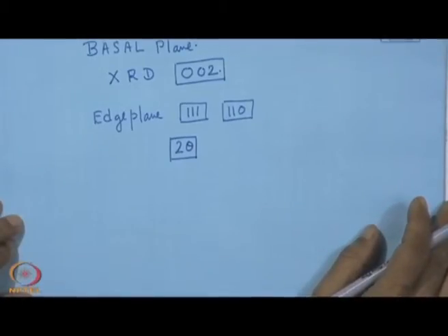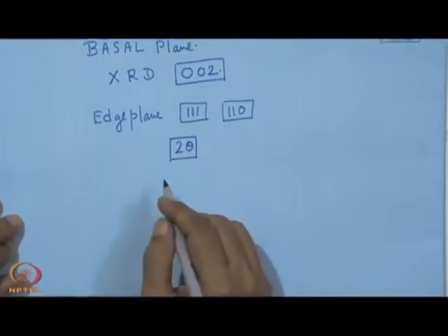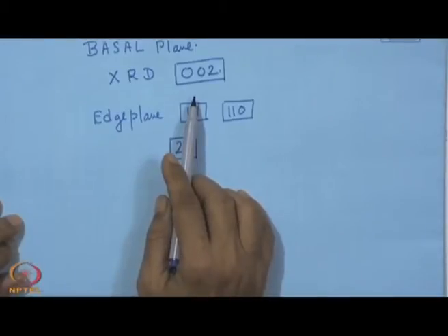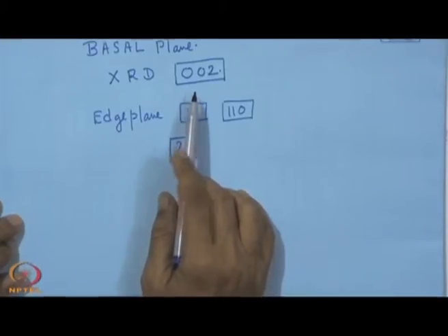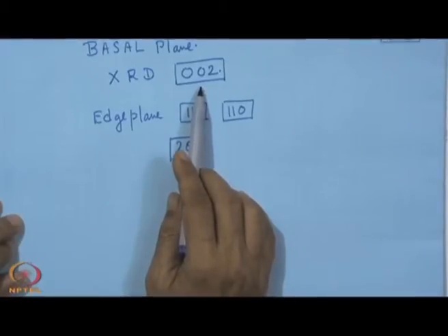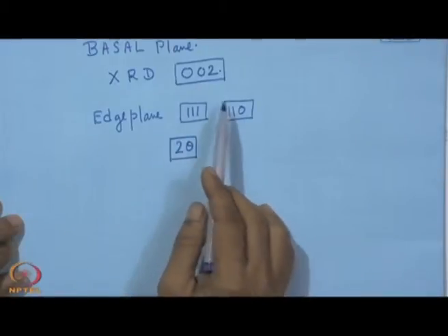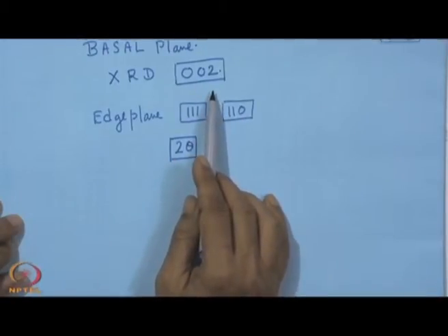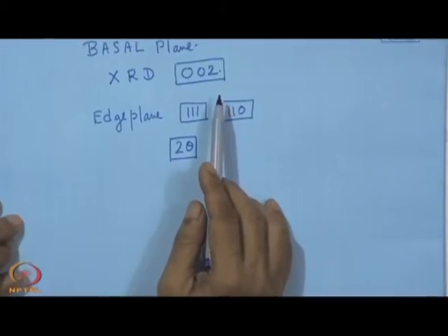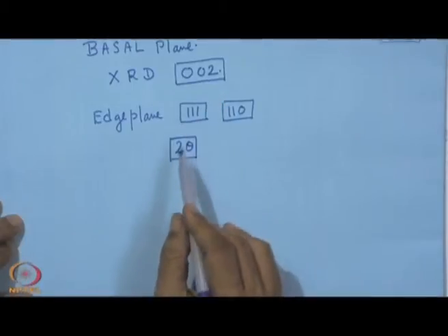have a fair idea, whether it is the effect of high cathode current, or wrong choice of process pressure, or the substrate bias selection. All these things can be known just by looking at the XRD diagram, at which peak is coming up, and depending upon the sharpness of the peak or the little widening of the peak, from there also we can have a fair impression about the size of the grain, fineness of the structure, apart from scanning microscopy.